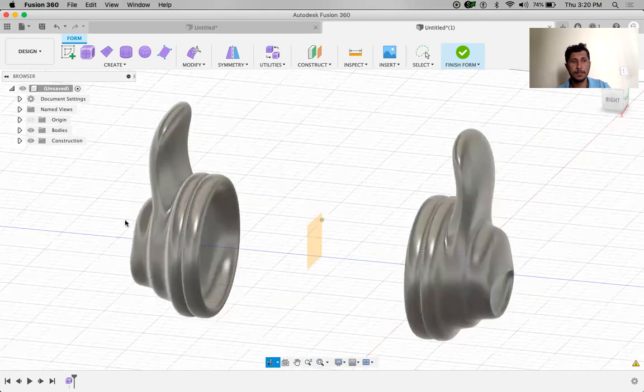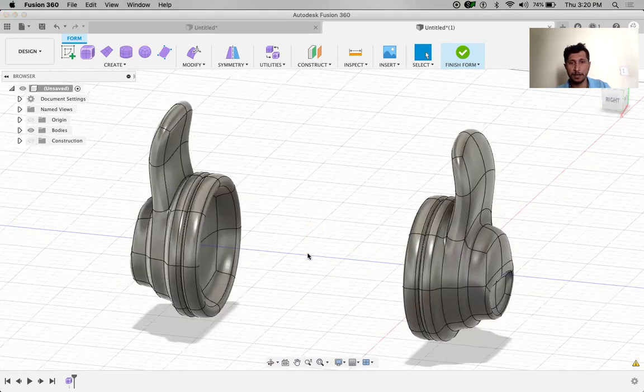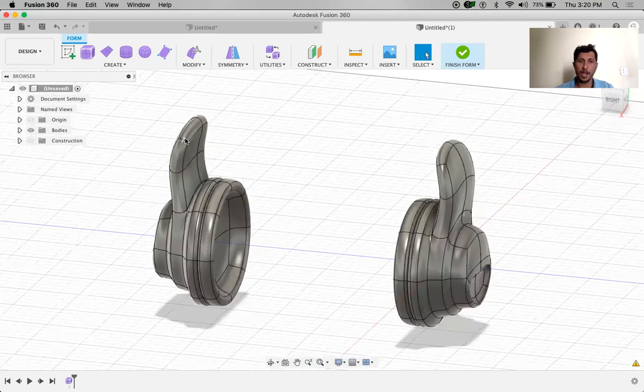Right. I can turn off the construction plane now. So visibility. Now I need to join these two. I cannot stretch, right? Even if I stretch this side, at some point those two have to exactly align. As I mentioned, if there's an overlap between faces, the software will not allow you to exit from freeform.